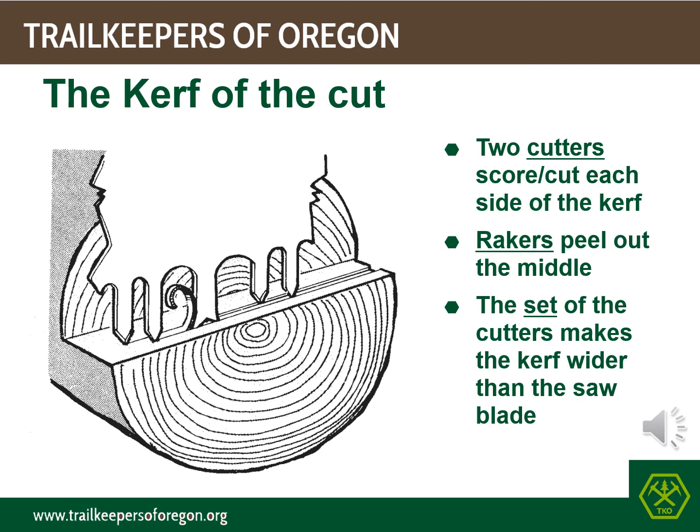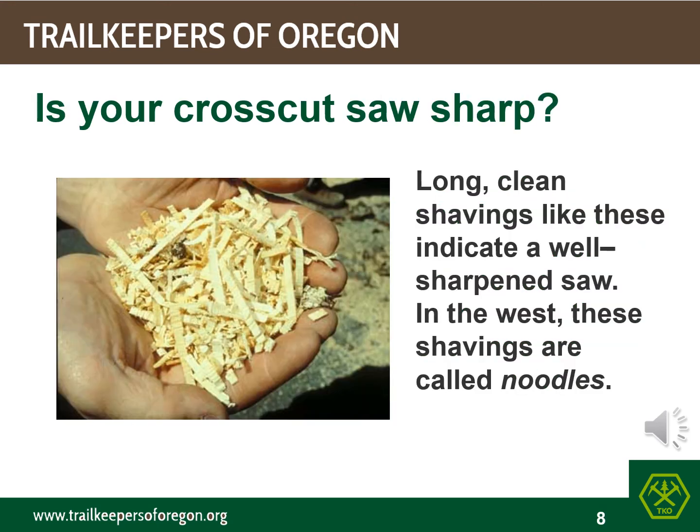Even when the fiber is dislodged, it clogs a saw cutter's teeth. With a little sawing experience, you will be able to feel the difference between different logs, especially green versus dry logs, as you pull the saw during a cut. If your saw cutters are sharp and set properly, and the rakers are formed correctly and are at the proper depth, the saw will perform smoothly and cut efficiently.